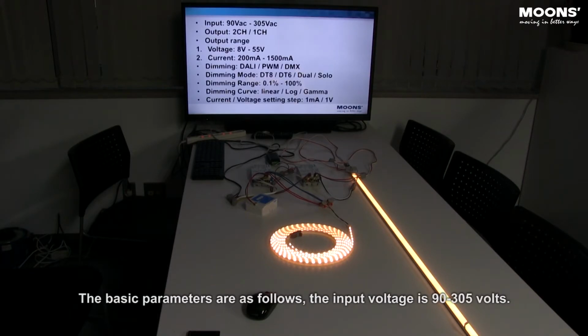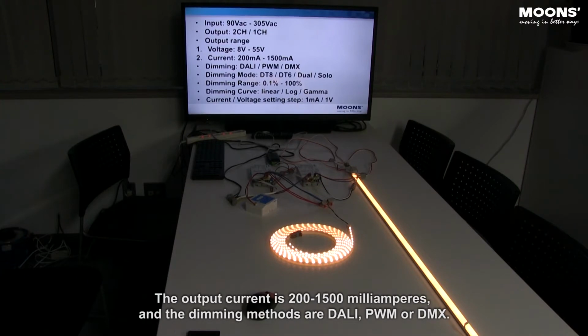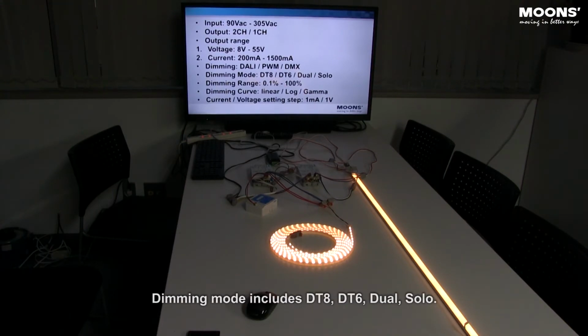The basic parameters are as follows: the input voltage is 90 to 305 volts, the output is 2-channel or 1, the output voltage is 8 to 55 volts, the output current is 200 to 1500 milliamperes, and the dimming methods are DALI, PWM or DMX. Dimming mode includes DT8, DT6, dual, solo. The dimming range can be from 0.1% to 100%.